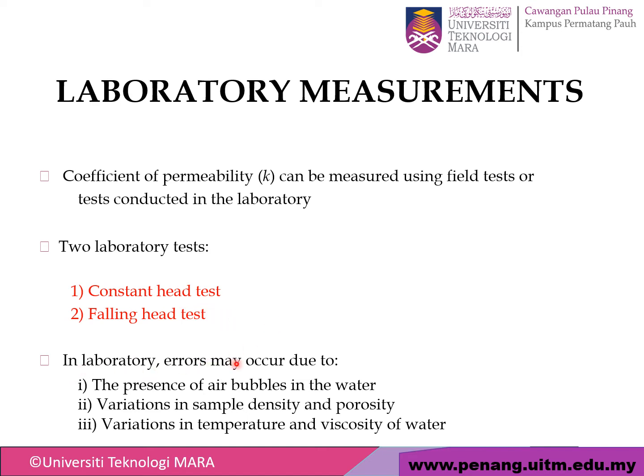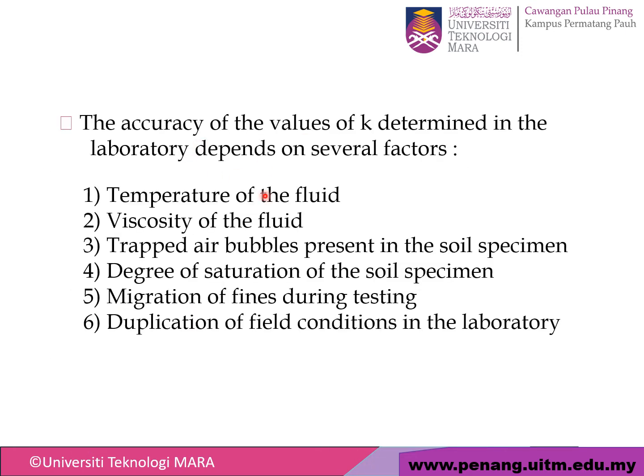In the laboratory, errors may occur due to the presence of air bubbles in the water, variation of sample density and porosity, and variation of temperature and viscosity of water. The accuracy of the value of K determined in the laboratory depends on several factors. The first factor is temperature of the fluid, viscosity of the fluid, trapped air bubbles present in the soil specimen, degree of saturation of the soil specimen, migration of fines during testing, and the last one is duplication of field conditions in the laboratory.